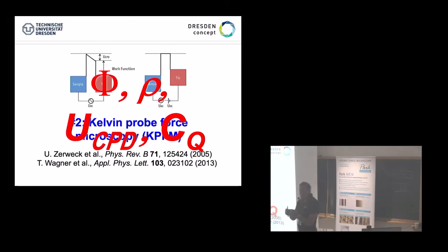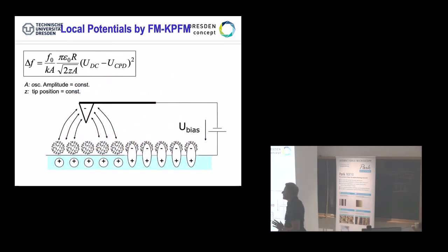And taking this principle allows you now to go for any frequencies. I will show you it's going to be a sideband modulation. We're going to just track a sideband of the cantilever, and hence with this we have a very high sensitivity. Let's start simple. The cantilever now, here's the bias. He's going to apply a bias, let's say negative, and hence we are inducing positive charges, which means we get a Coulomb force. If the charge here would be positive, it would also be a Coulomb force interaction that is attractive, simply because then plus the induced charge would be minus.